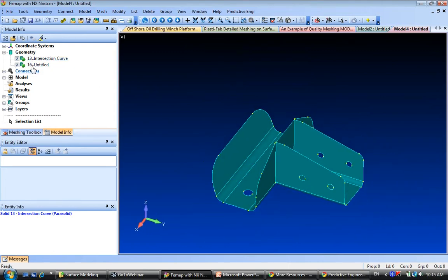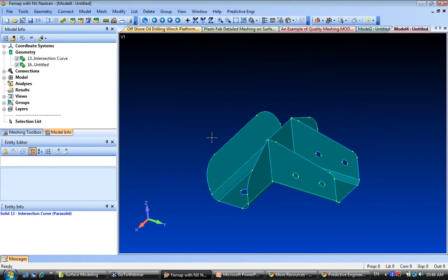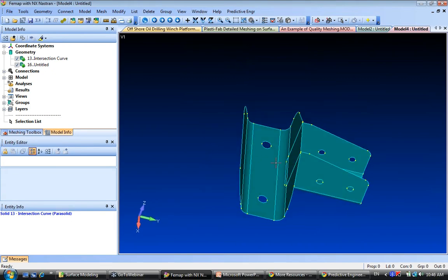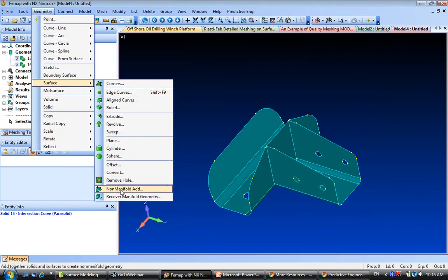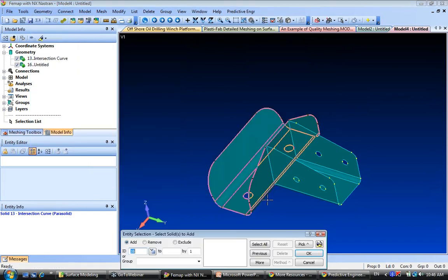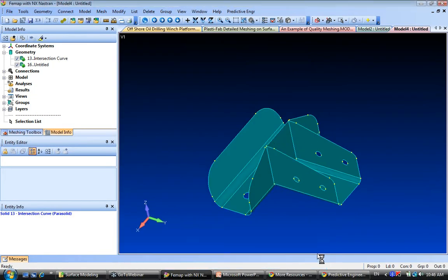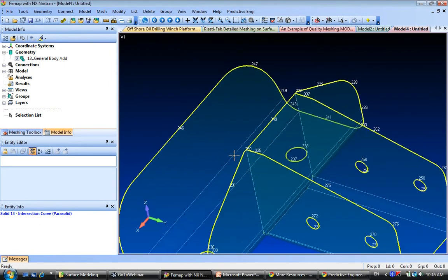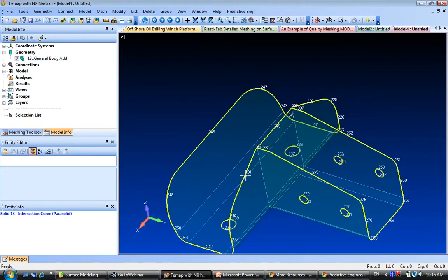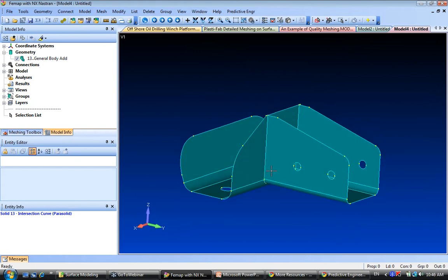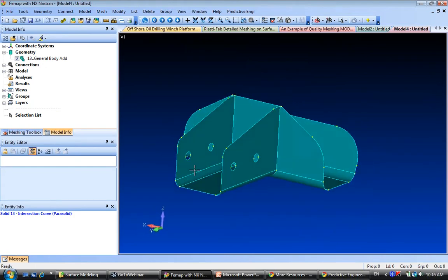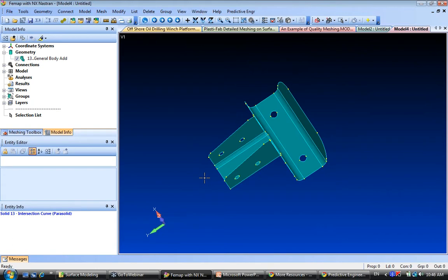Now, we still have 2 pieces, and meshing could be difficult because lining these 2 up and fighting with that. This is a wonderful tool. I use this all the time. Non-manifold add. What's this? Voila. It seals them. You now have one general body. Gets rid of all your meshing problems. Joins up, sealed, it's happy, connected, congruent, all set.